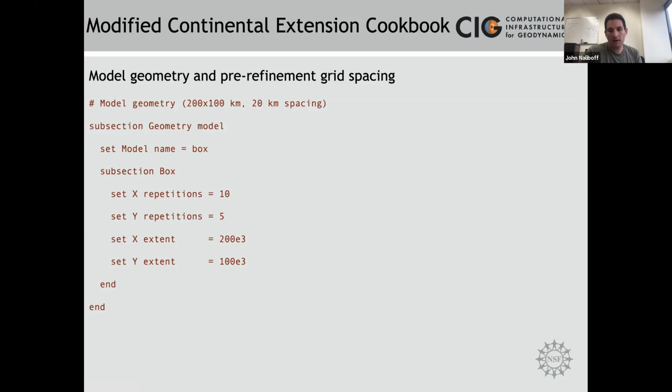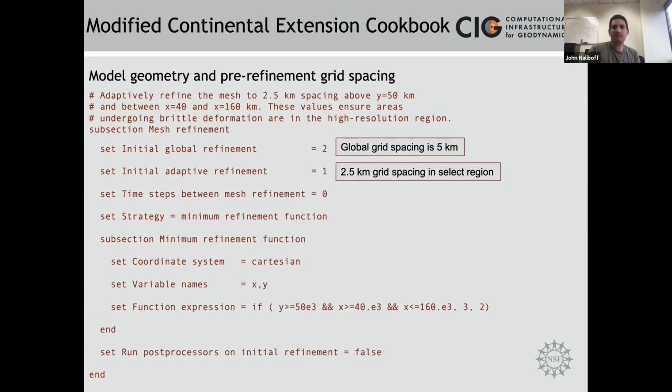In general, for lithospheric dynamics problems, or basically any problem, you normally do not want to start out with a scenario where your elements are distorted. So you have, let's say, 40-kilometer spacing in the x direction and 20-kilometer spacing in the y direction. You almost always want to have equal size elements because otherwise it's going to distort things like the angle of your shear bands.